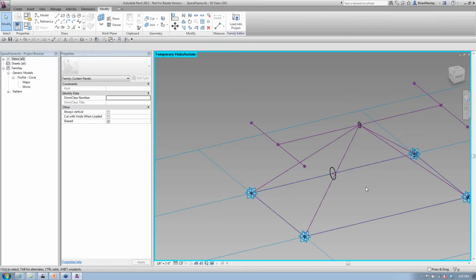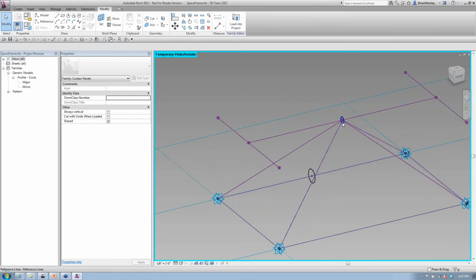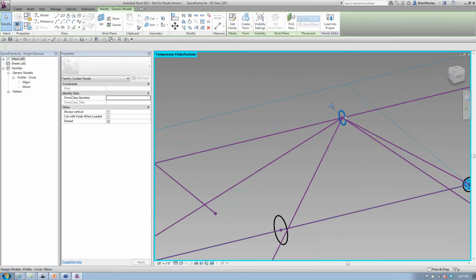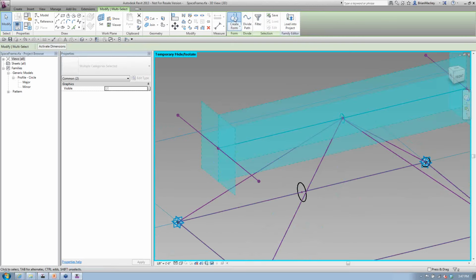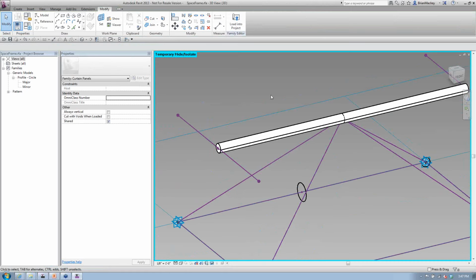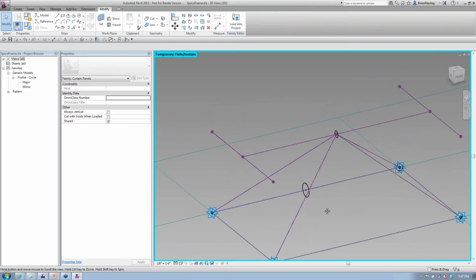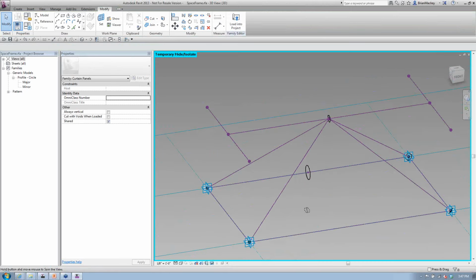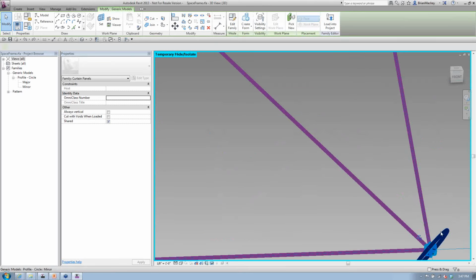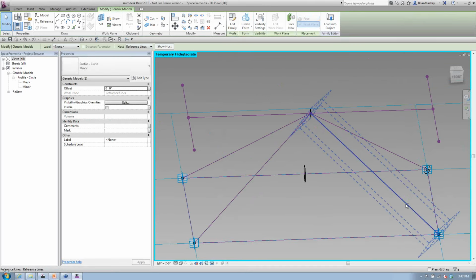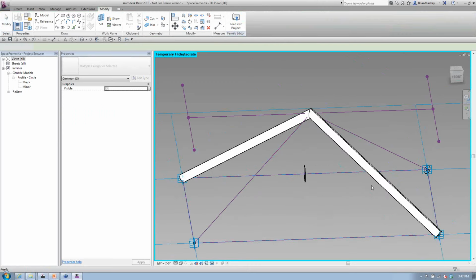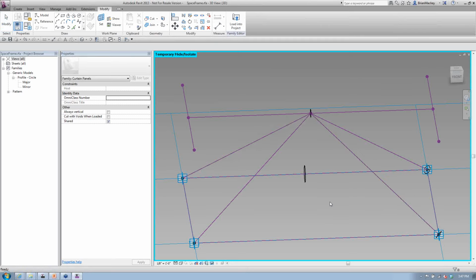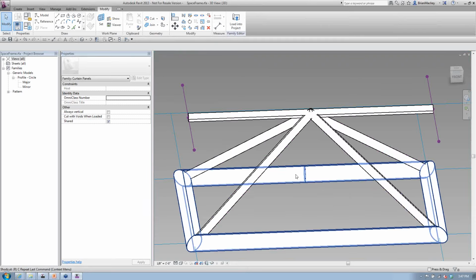But what's different on this one is I simply took these, drew some circles on there, took the circle and the line I wanted and said create form. Okay, I'm going to undo that because I already have multiples of those. So same thing down here. If you start looking, I hosted a point on this line, then I could come in here and probably grab it over here as well and say create form. So I went up and over, just created all of those forms, and this created my mass.